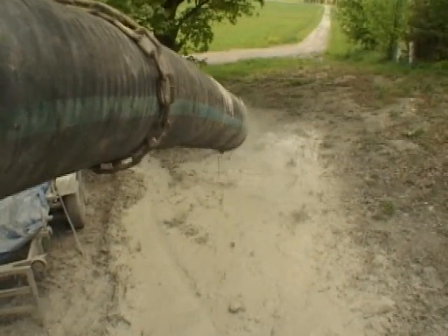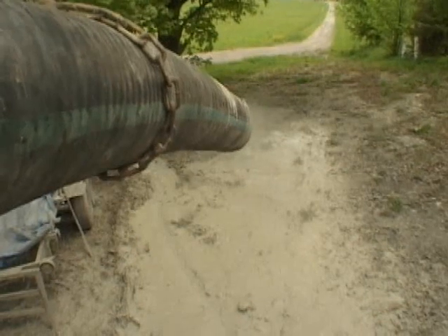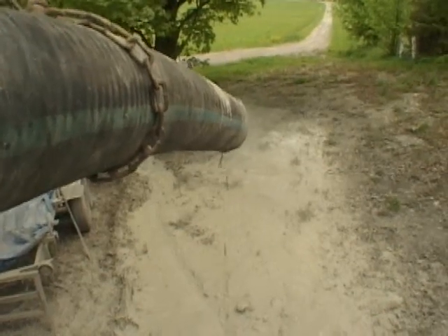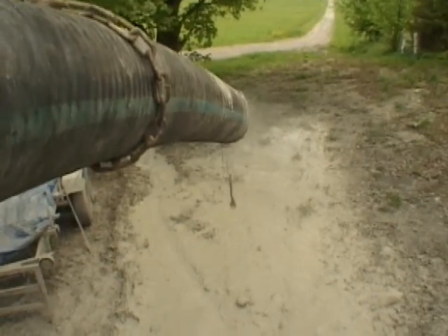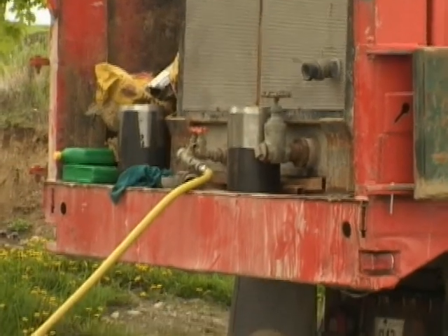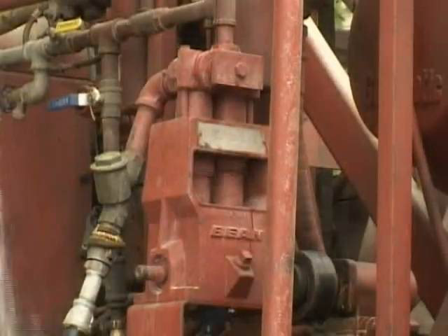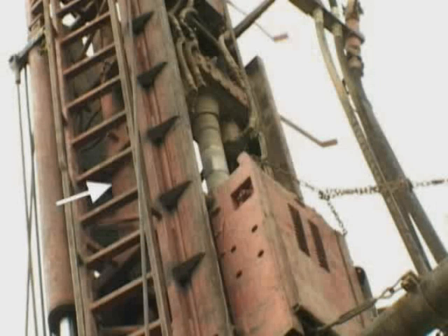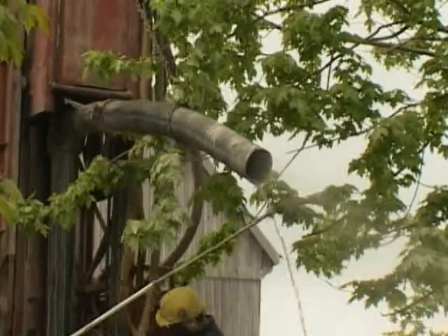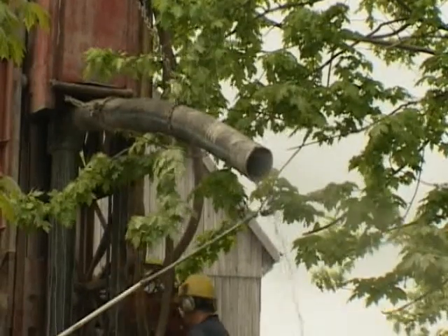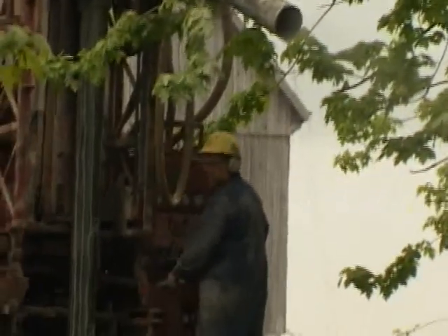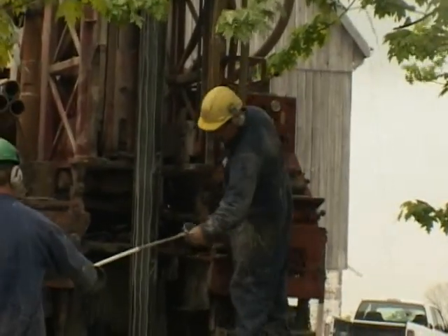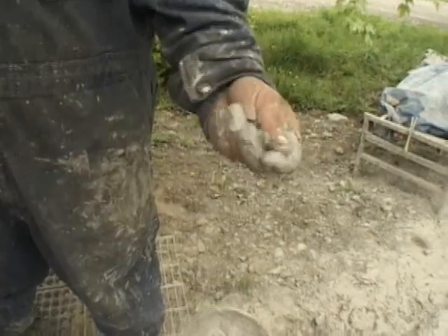Air is utilized to flush the cuttings. Water is being injected to enhance the air's ability to remove the cuttings and control dust. The water is pumped from the support vehicle through an injection pump, down the drill string, through the bit, and back up the inside of the casing to the casing driver, and then out onto the adjacent ground, where the technician can obtain samples which are very representative of the geology encountered.